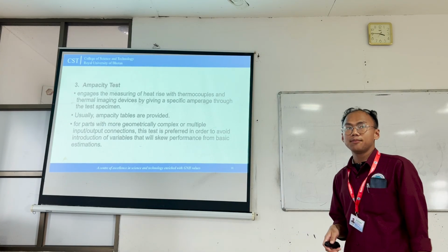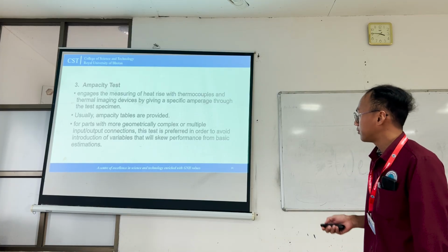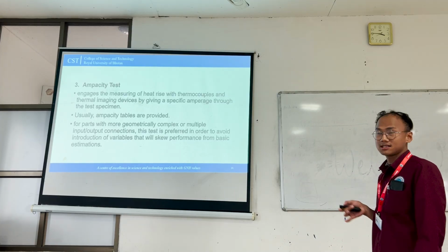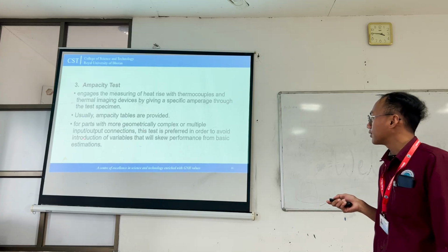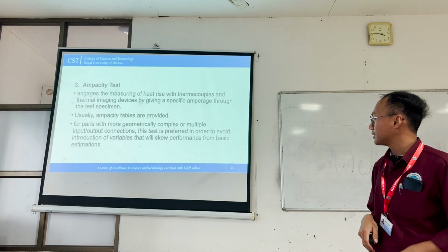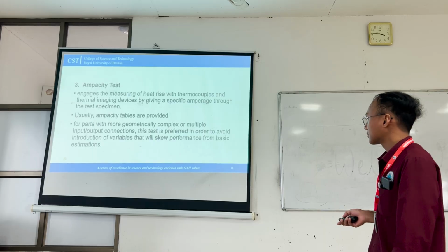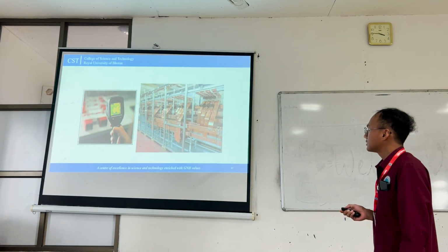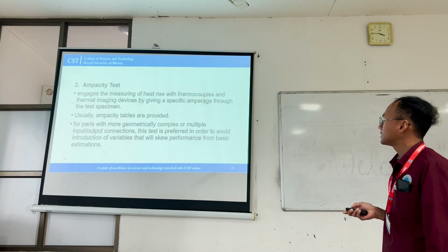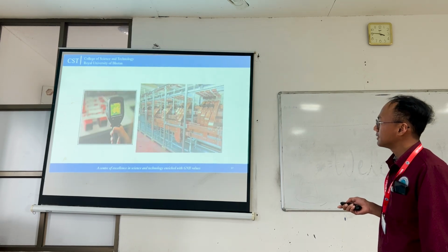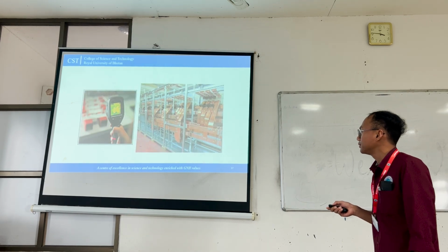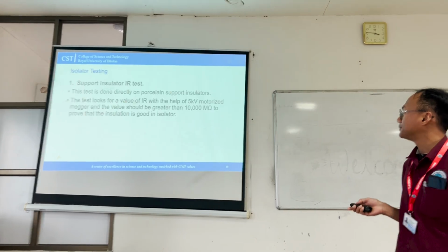Usually for this, an ampacity table is used, but for parts that are more geometrically complex, this test is preferred in order to avoid introduction of variables that will skew performance from basic estimations. This is the overview of the ampacity testing. This is the thermal imaging device that is being used to do the test.